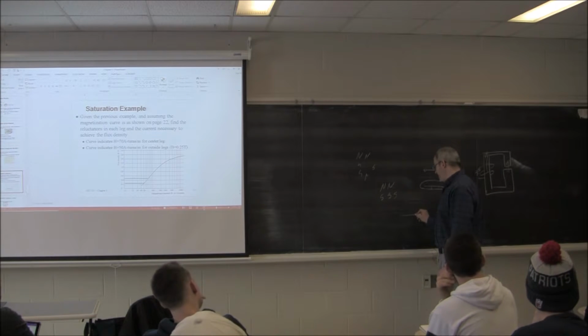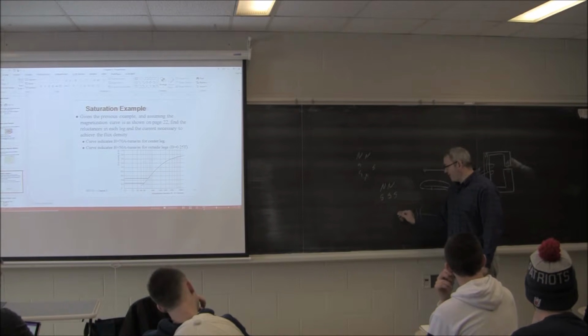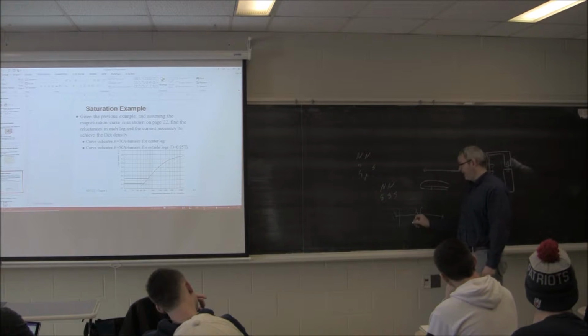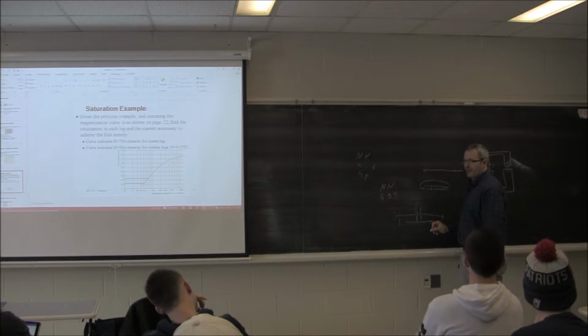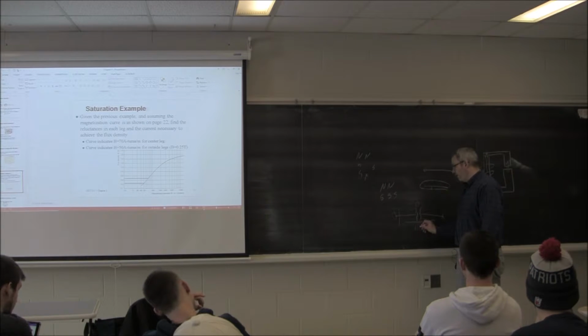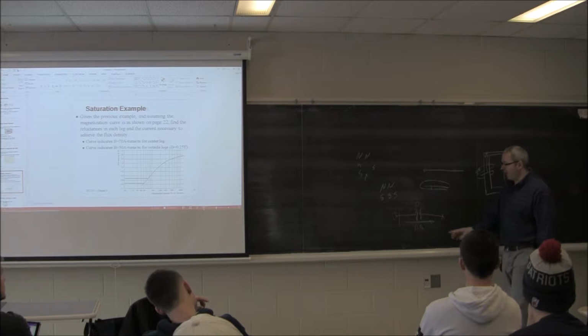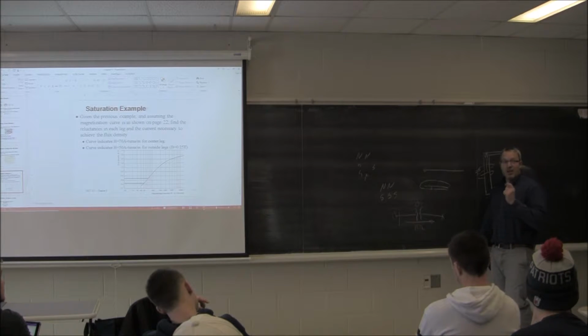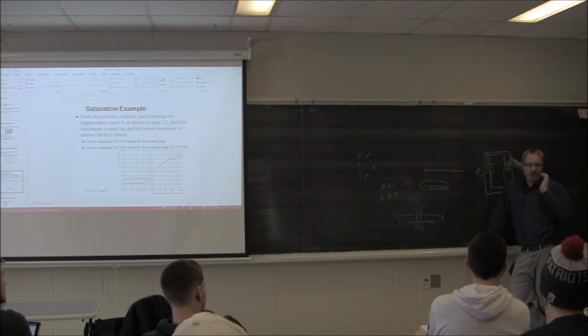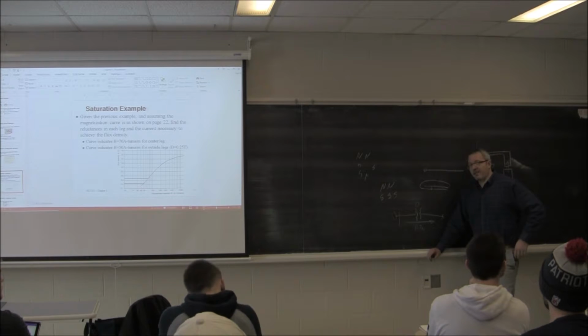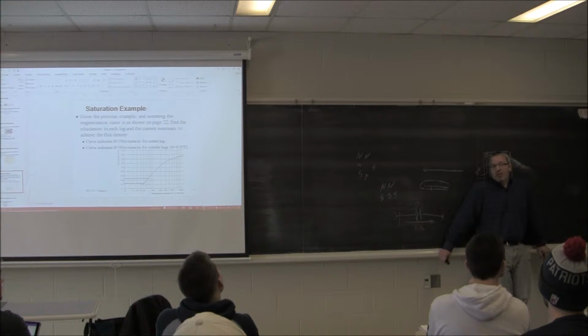Well, a perfect example is here into campus. If I have Bangor Hydro, which is big bad Bangor Hydro, and I'm connecting over here and I get a fault, I get tons and tons of energy here, if this is at 0 ohms. By putting this at 10 ohms, you limit the fault current. A lot of times you actually specify the impedance to knock down the level of fault current of your system. It also has to do with the stability of a system for bigger generators, but more often than not, you specify some of these transformer sizes to knock down the level of fault current.